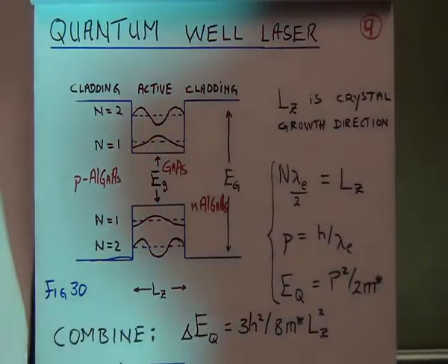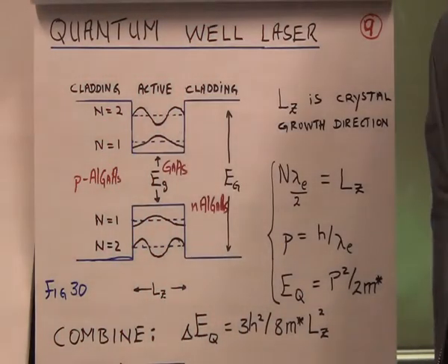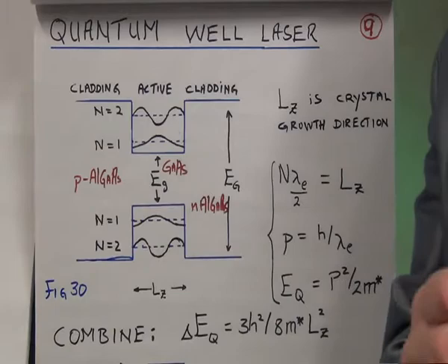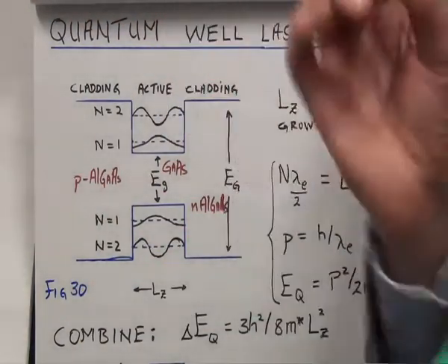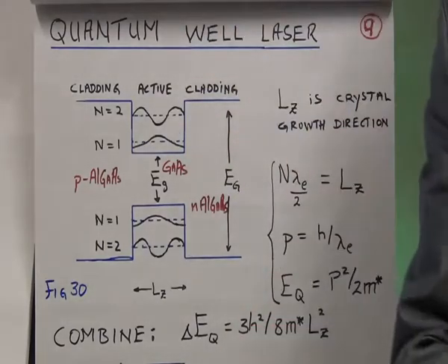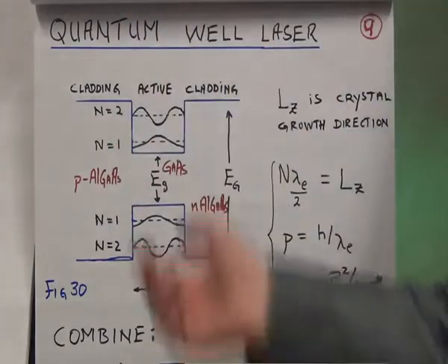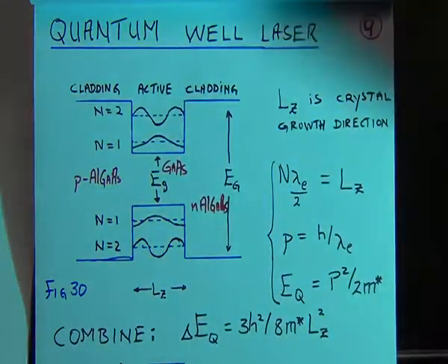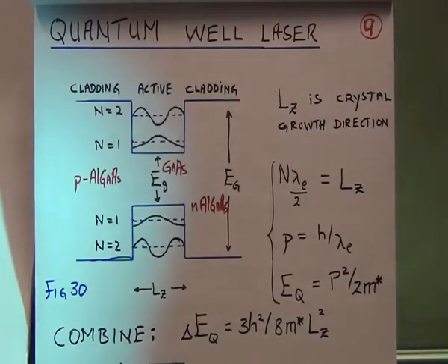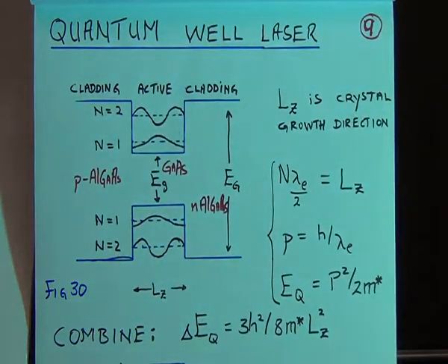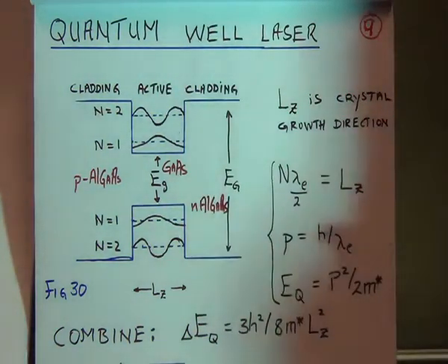If you have a very, very low threshold, instead of tens of milliamps, if you had tenths of milliamps or lower, inside your computer you could have thousands and millions of these lasers talking to one another optically, and the currents are so low that you can actually manipulate data with AND gates and NAND gates and adders and subtractors and whatever you want. So you have the basis of a photonic computing. Low threshold can get us to that stage. And that is a target which is very interesting for supercomputing.